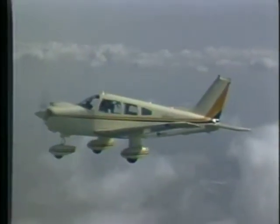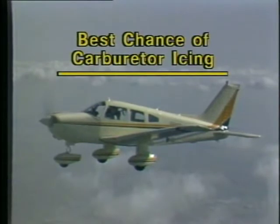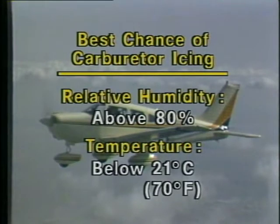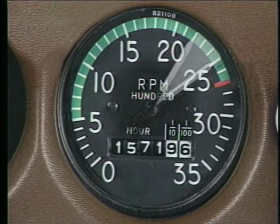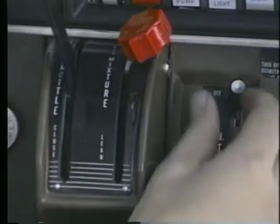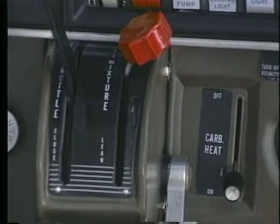Although carburetor icing can occur over a wide range of conditions, it is most likely to form when the relative humidity is above 80% and the temperature is below 21 degrees Celsius or 70 degrees Fahrenheit. In most training airplanes with a fixed pitch propeller, the first indication of carburetor ice and the subsequent power loss is a gradual decrease in engine RPM, which may not be readily noticeable. If this situation occurs, you should apply carburetor heat. This routes heated air into the carburetor to melt the ice.